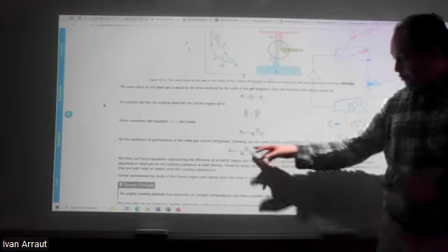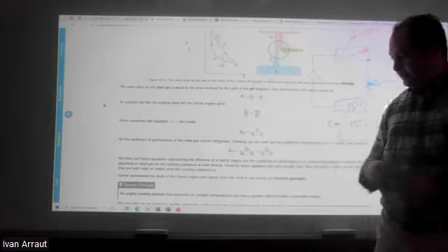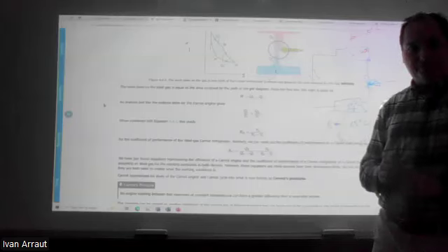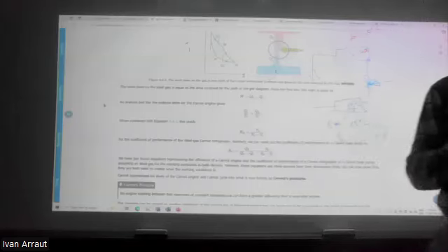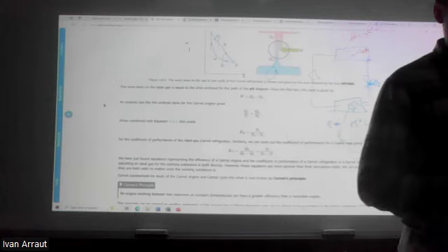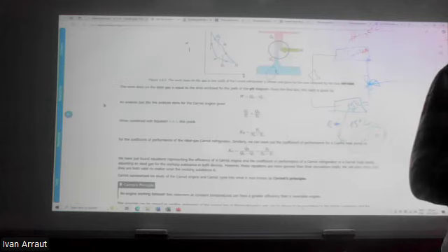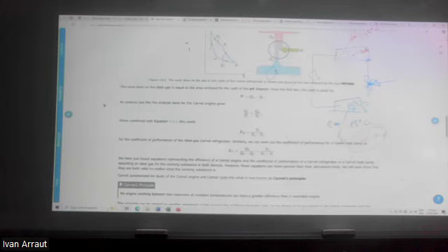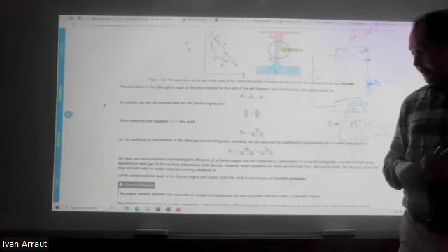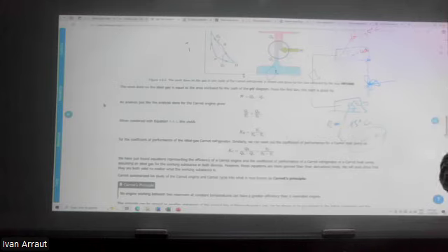So what do you have to do for increasing the coefficient of operation? Remember, the efficiencies are normally smaller than 1, but the coefficient of operation has to be larger than 1. So if I want to increase the performance of the refrigerator, what do I have to do?